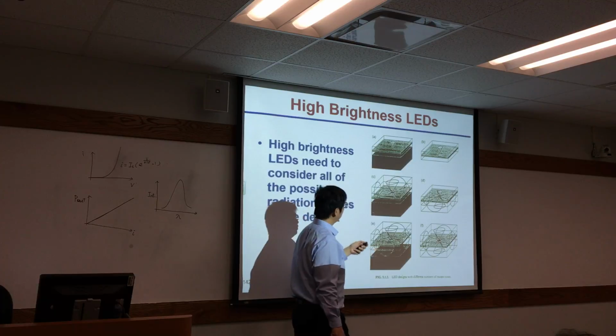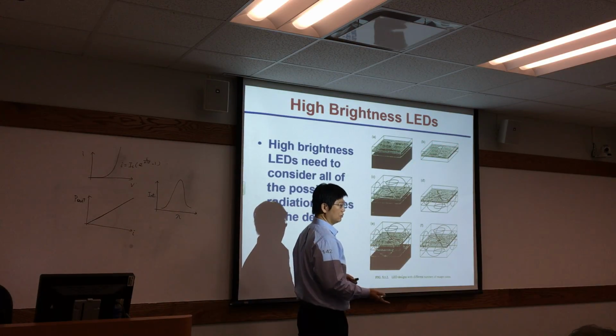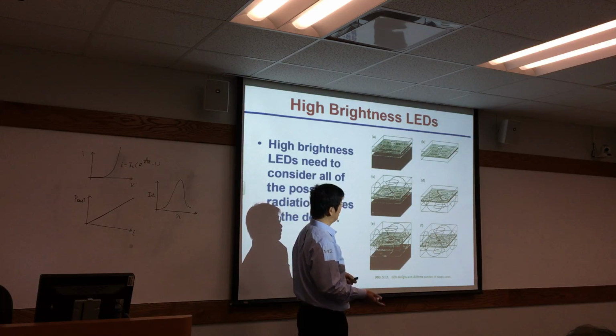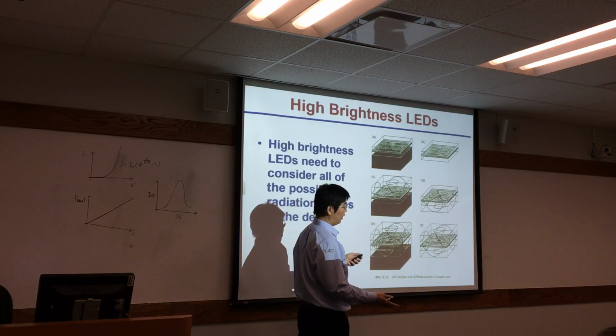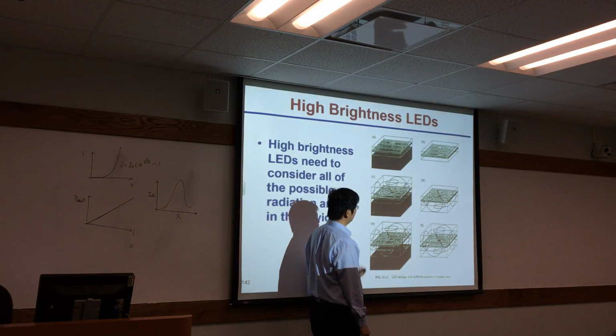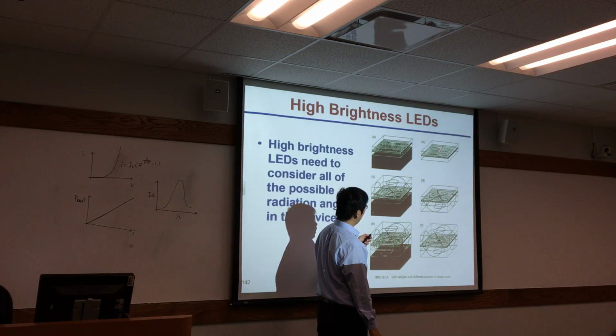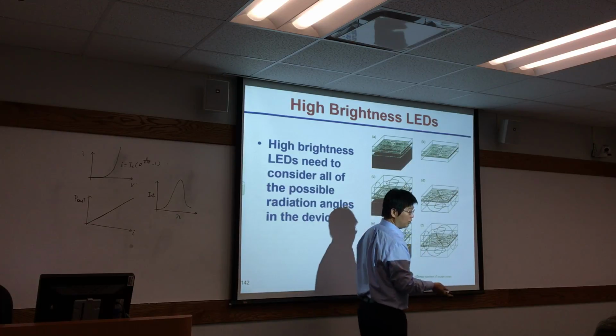And the LED chip dimension is about 300 micron, 500 micron, something like that. And the epitaxial growth here is typically about 10 micron. So if you have some LED epitaxial growth, you will know that it's about 10 micron. So it's 10 over 300. So when the light propagates to the side, there's probably a lot of loss.